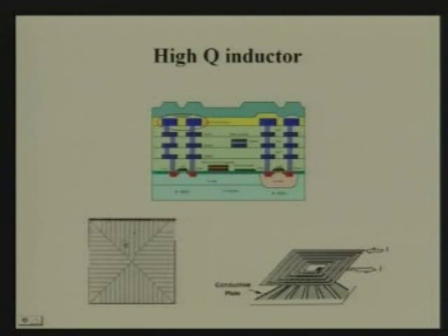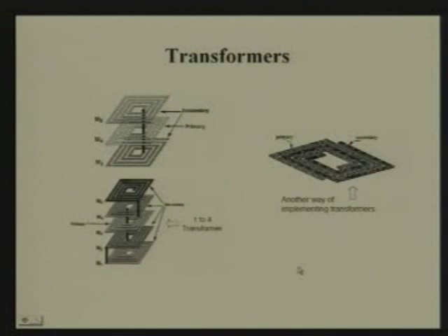However, if we just keep a planar shield, just a sheet of metal, then that will also have induced currents flowing through it. Hence we divide the strips in such a way that it does not hamper the current flow in this inductor. The primary technique is to divide it radially into wedges as shown. This is called a patterned ground shield. It's almost there in most RF CMOS processes. It's ready for the inductor. Okay.